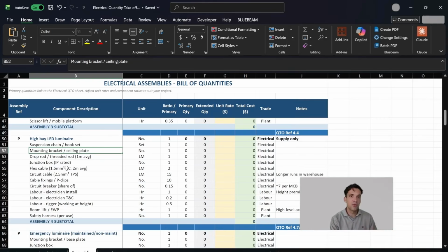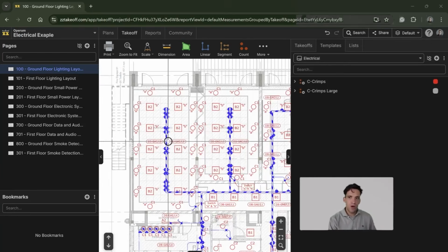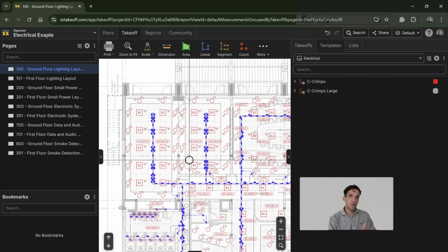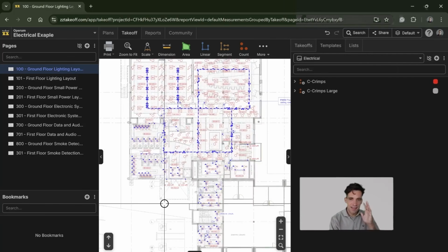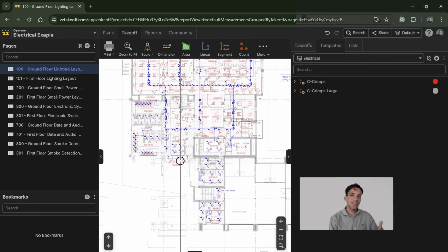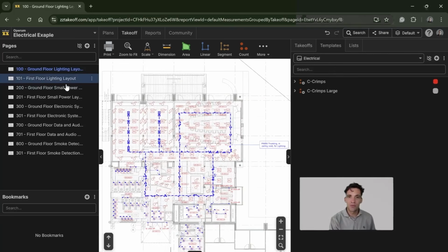If you're doing this for procurement and for the purpose of buying the light fittings, that doesn't actually matter. But if you're doing it for construction and installation, you have to think about what all the different productivity rates, access requirements, and plant requirements are that we'd need for these different tasks. So to make this really simple, I'm going to do 2 examples, one of measuring light fittings, the other for measuring linear meters of cable tray. And again, the actual measuring act is the easiest. The bit you really have to think about is how you set up your individual assemblies.